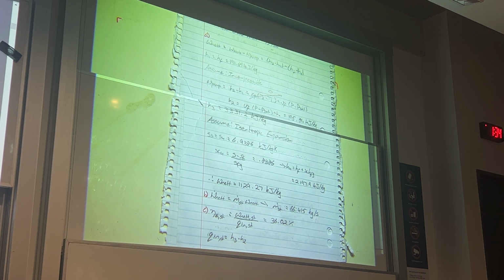So the big connection you have to make here is that once we get to this temperature here, we've started boiling the water. If you were to plot this graph in time, this second line would go in the opposite direction because our water is increasing in temperature as our gas is decreasing in temperature. So what you need to know is this pinch point temperature is when our water starts to boil.